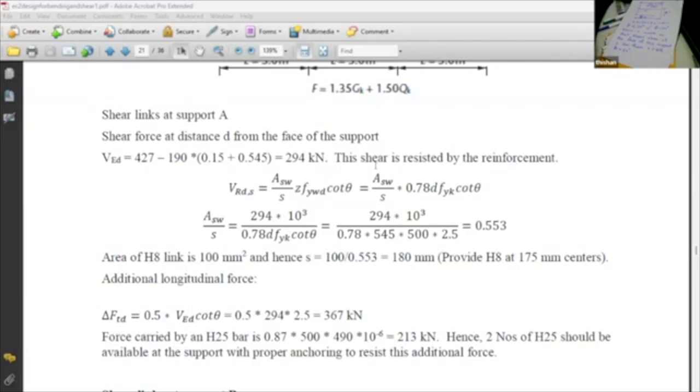How could I make the shear capacity excessive? I use a wider beam, not a very narrow beam. In a very narrow beam, shear capacities are low. In a wider beam, shear capacities are high. If the beam is heavily loaded, I will use a wider beam. If the beam is very lightly loaded, then shear is not critical anyway. Have you got the point, Banduka? Yes, sir. That is clear.